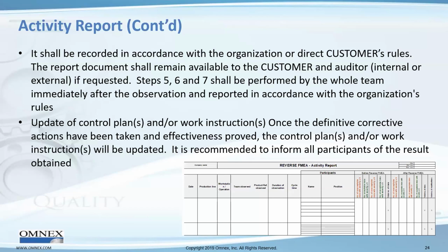So what I've seen just recently, I saw a client where all the occurrences were 3. And when I asked them why all the occurrences in their PFMEAs were 3, they said, well, look, and they had their automated form up on the TV. And they said, when we move it to a 4, we've got to take some action. So they were focusing all of their level of occurrence and their level of detection on the impact on whether they had to take some action or not.